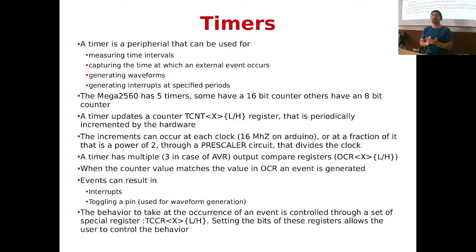If you're interested in super accurate timing, you could use a timer as a peripheral that stops counting when a certain value of a pin is received. So in this other way, you have a timer in freely running mode. You configure this digital device to say, hey, monitor this pin, dude. Start counting. When this pin changes status, for instance, stop counting and send me an interrupt. In this way, the timer freezes the time, and then in your interrupt routine, with all the calm, you can go there and read how much time has passed. This is the second way.